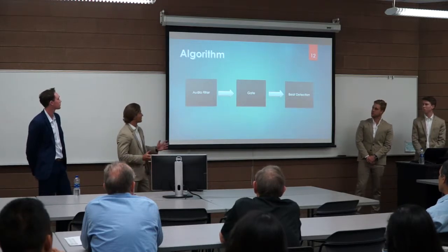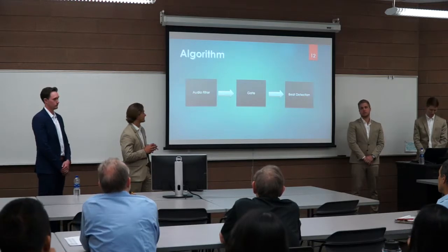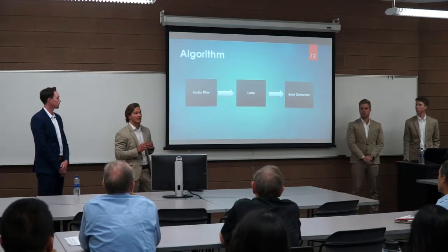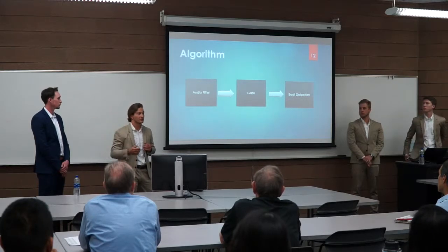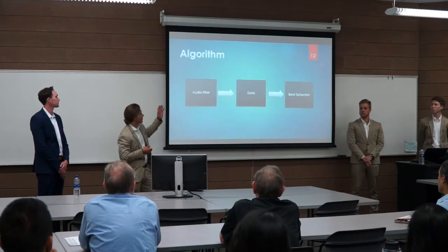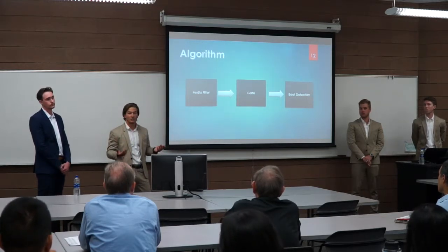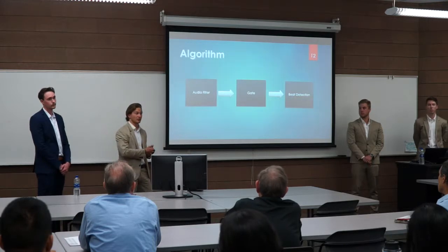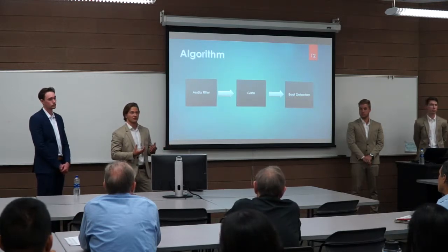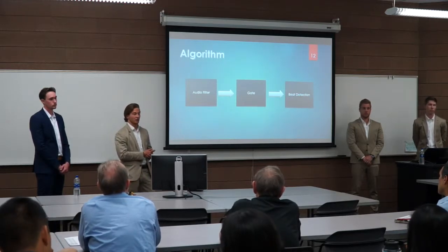First, when the .wav files come from the sampling from the microphone itself, we have to filter out all the audio, because we have all the other instruments playing, and we want to focus on the kick drum that determines the BPM. Then we throw it through a gate, also known as a threshold, so that once we hit a certain threshold for the dB, or the loudness level, if you guys aren't familiar with dB, we know when the actual kick hit.